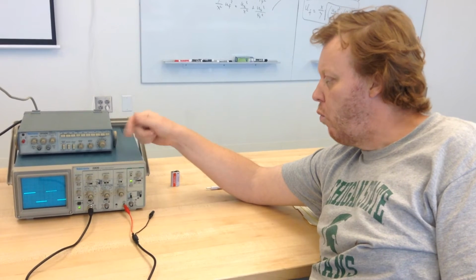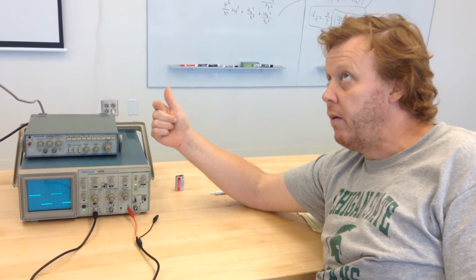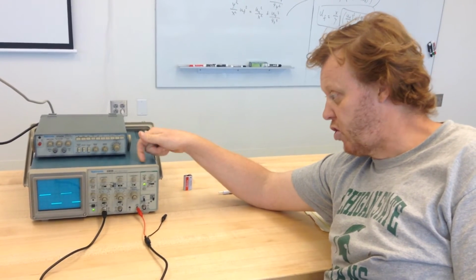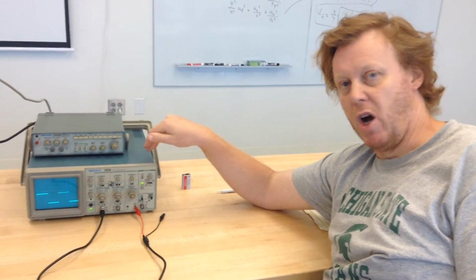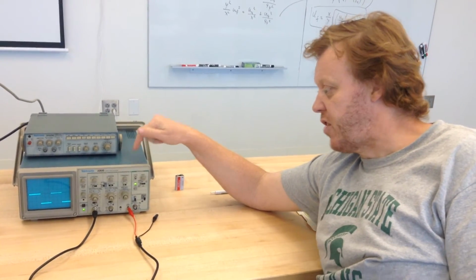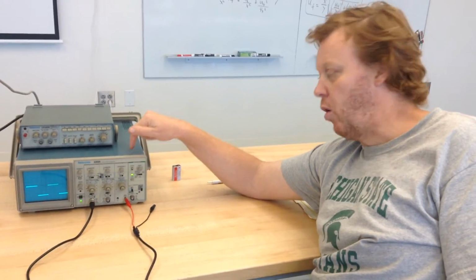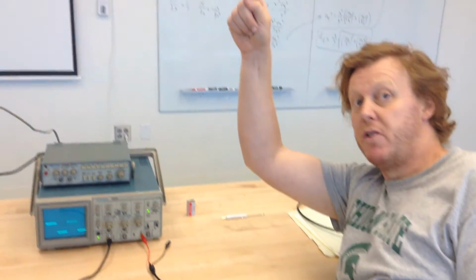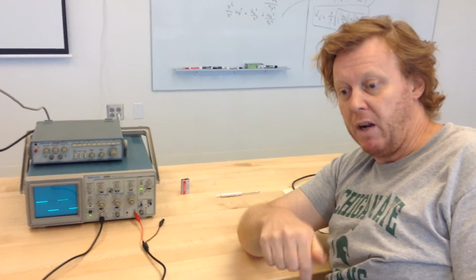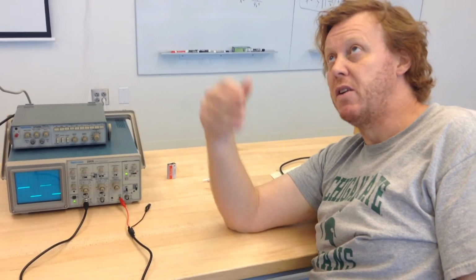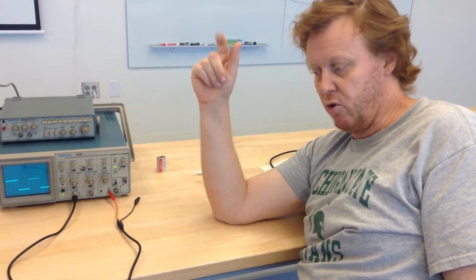If a wire that was connected to the electric cable touched this chassis and you touched it, you could get a shock. So there's a solid connection, a solid metal going from this chassis all the way to that big metal rod stuck in the ground. That's called grounding. The third fat pin on the 3-pin plug is to achieve this.